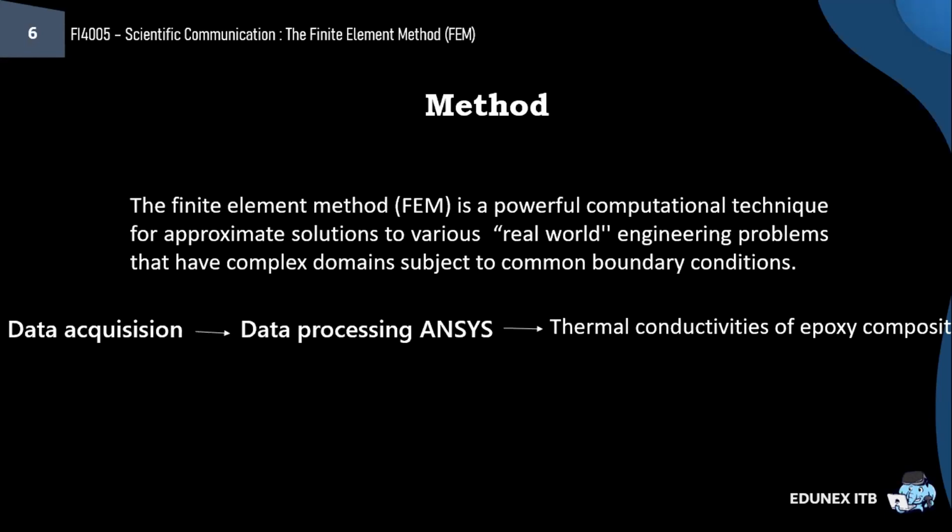The heat equation is solved numerically using the finite element method with the linear quadrilateral element, which has 4 nodes. Using the finite element program ANSYS, thermal analysis is carried out for the conductive heat transfer through the composite body. In order to